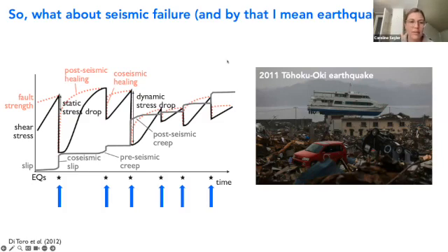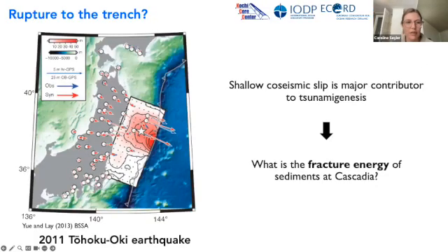In this particular example of the 2011 Tohoku Oki earthquake, there was significant damage because of one unusual aspect about this earthquake. In this event, they had a larger than expected amount of slip on the really shallow subduction interface, up to, I think, maybe 50 or 60 meters of slip on the shallowest portion, which is not what's typical. Normally, you'd expect the slip to be concentrated in the center of the earthquake patch.